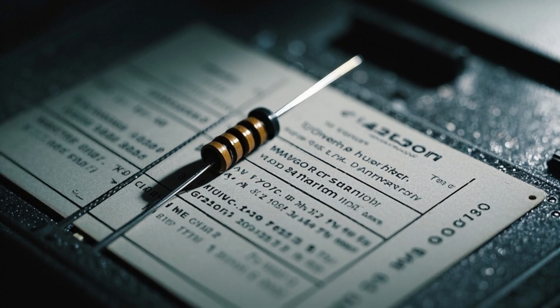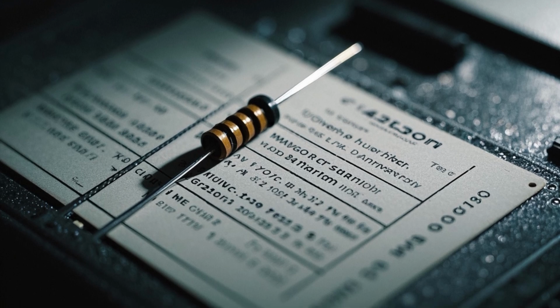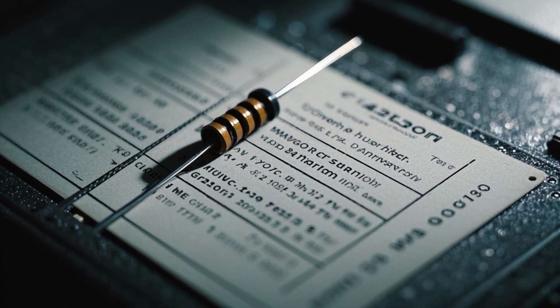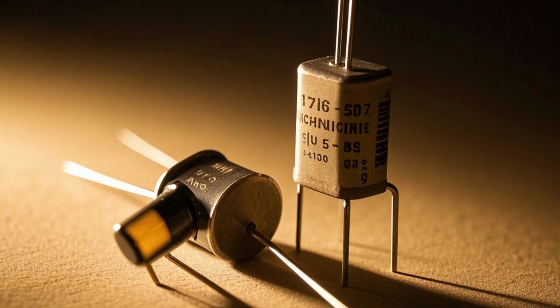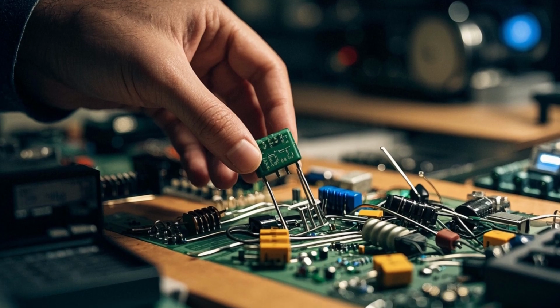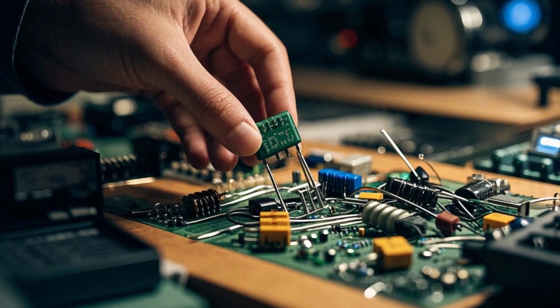So it's important to choose a resistor with a high enough power rating for your application. You can use the following chart to get an idea of what power rating you will need for your resistor based on the wattage or power being dissipated by the resistor. The higher the power rating, the larger the resistor needs to be. So now that you know the basics of how resistors work and how to read their values, how do you actually pick one out for your project?